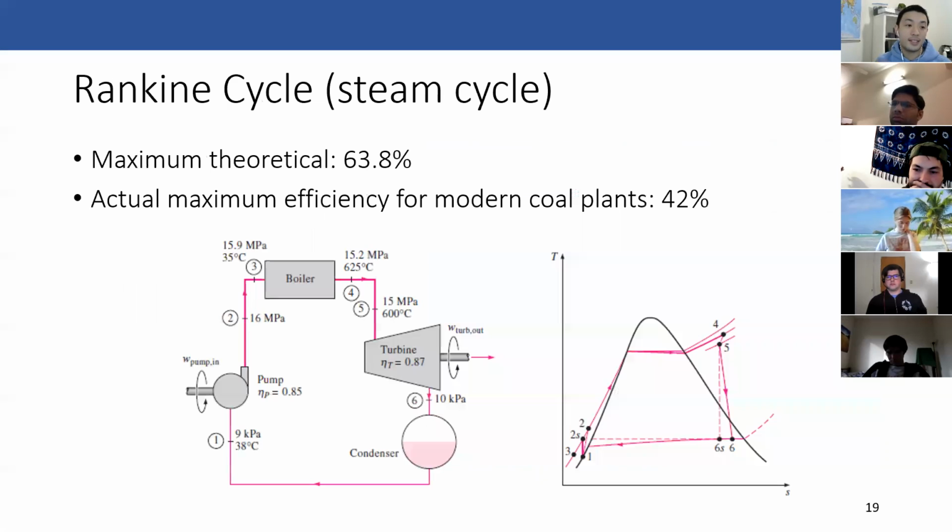So the way that steam turbines work, you have the combustion of your fuel that will heat up water in a boiler. The water in there will reach extremely high temperatures and pressure, and it will get sent through your steam turbine. Okay, and then what comes out at the end is much lower pressure and temperature water, and I should actually just say steam.